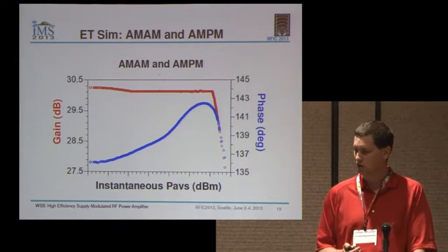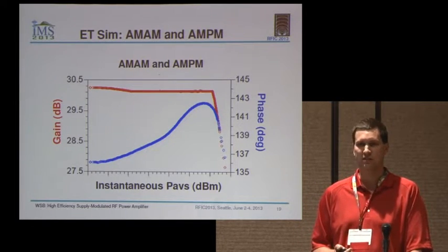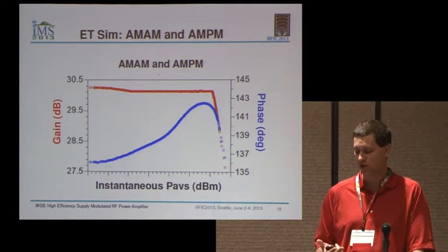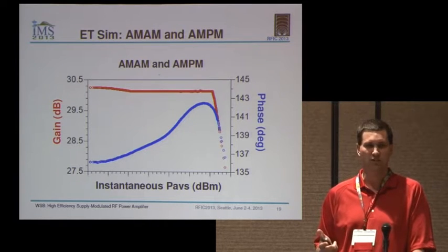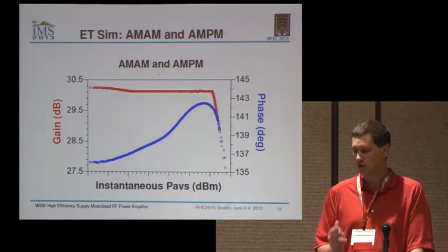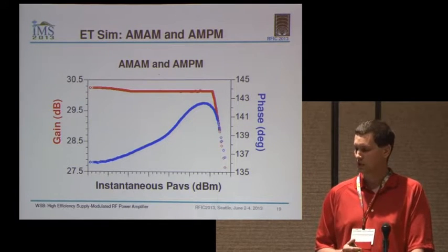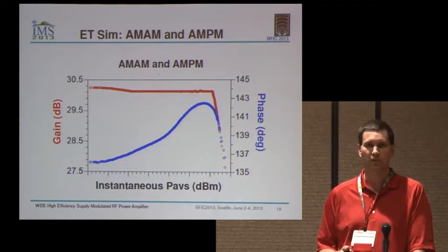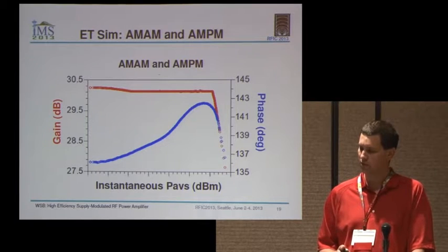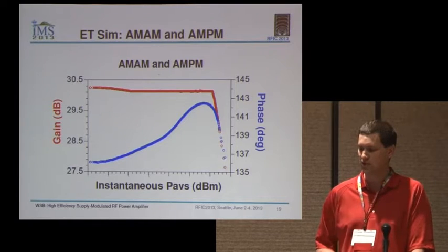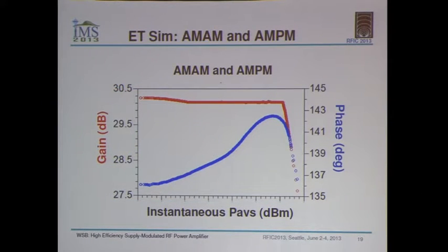And then towards the high end of the curve, we encounter the VCC max clipping level. The voltage on the collector can't go up any higher, so we fall onto whatever that max VCC curve is, we fall onto its gain curve, and our gain drops off. It doesn't drop straight off, it still has some shape to it, but we are clipping the peaks. On the low end also we can see the effective clipping. In the lower, probably 1/4 of the gain curve, the gain actually rises slightly above the 29.8 dB, and that's the effect of the minimum clipping being incurred.